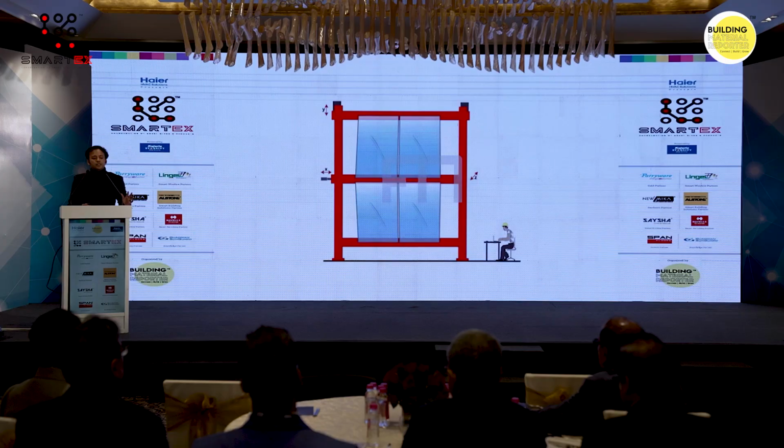So there's dampers. I don't know if you see in this image, but 32 dampers have been installed, which are like shock absorbers on the lower 4 floors. And then the glass, because it's an immediate occupancy building, glass usually moves horizontally or vertically. So the glass system which we proposed is moving in all these directions to counteract the movement and thrust of the earthquake, so the glass is not breaking. Otherwise, 80 to 90% of a building's glass will shatter during an earthquake with all the forces it has to encounter.